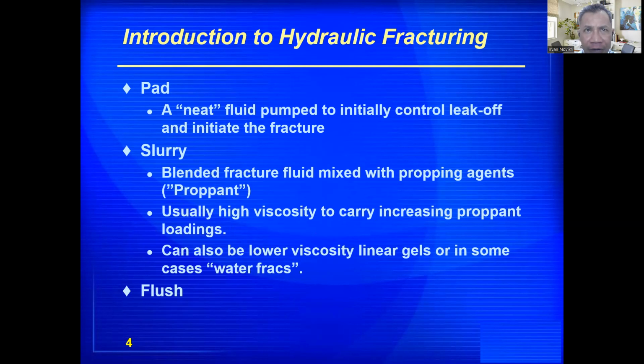The fracture treatment basically consists of three main components. The first is the pad, which is very important. This is neat fluid, meaning that it contains no proppant. It is usually the main fracture-creating fluid. It is pumped to control the leak-off, because you have to remember that we are pumping this fluid into the porous rock medium. So we are pumping in at this high pressure, and some of that fluid is leaking off into the rock. Okay, so we initiate that fracture.